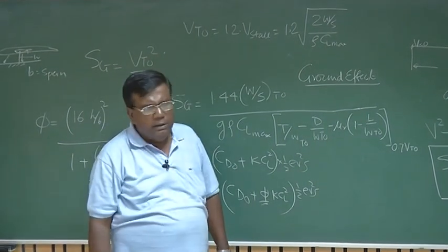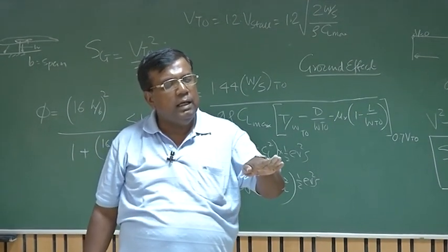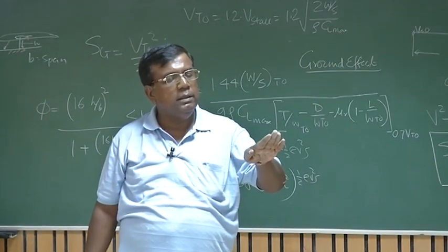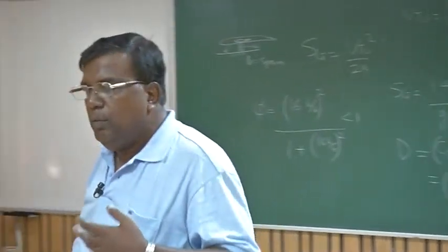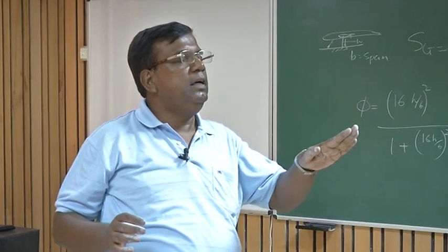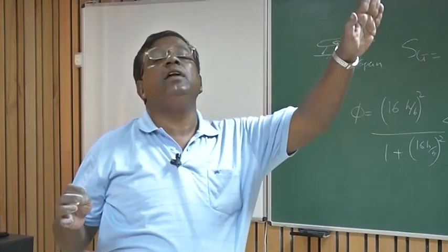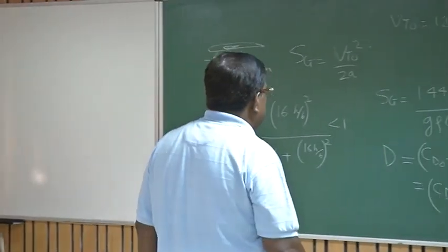Another question comes, when the airplane is going like this and starts taking a turn like this, we call it rotate. How much time is allowed to rotate the airplane? For all practical purposes, it's not more than 3 seconds. So rotate, then transition, this whole thing, sometimes for a high T by W aircraft, you may find they're happening at one time. They're going like this. You won't be able to distinguish. Okay? But we need to cater for those.